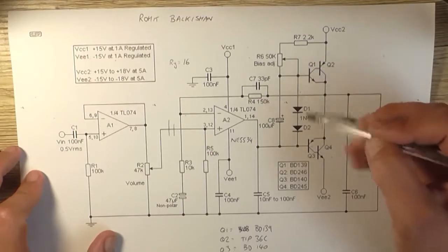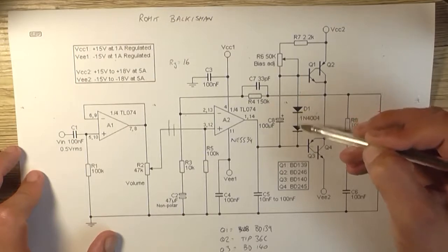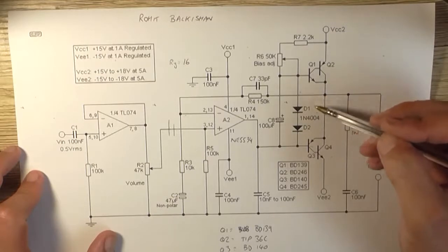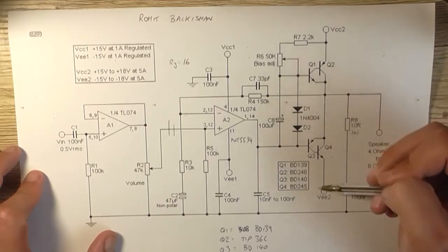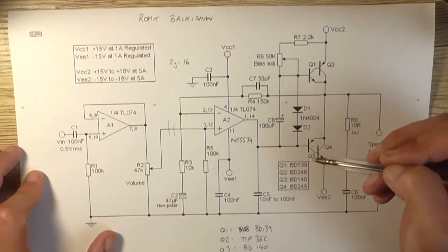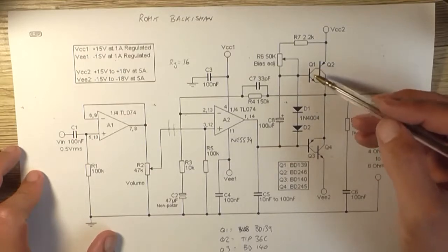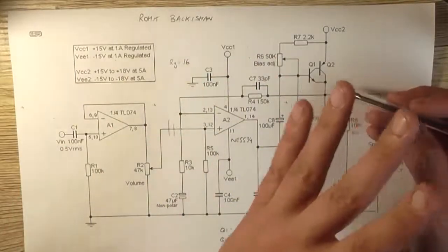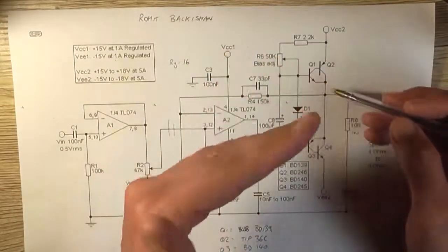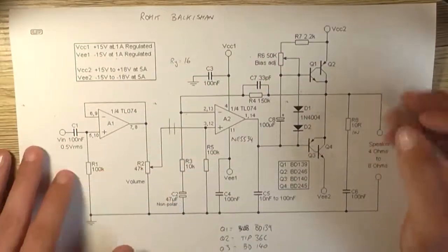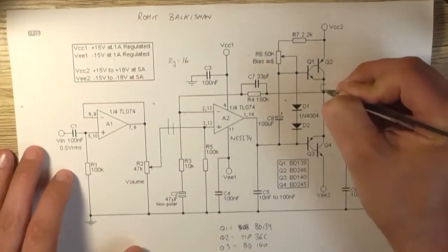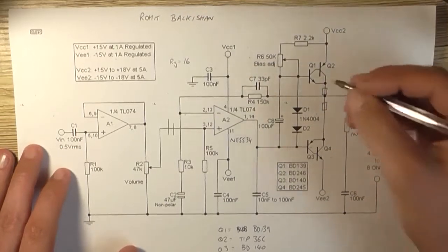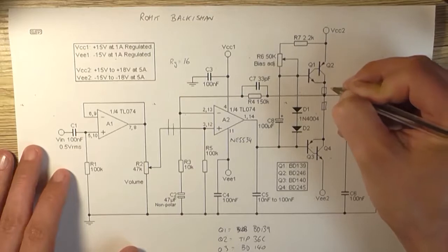Once the transistors heat up, the diodes conduct more, the bias goes down, and so therefore does the current flow through the circuit go down. What that means is it's to try and prevent thermal runaway. So once it starts heating up, it drops the current down to limit the amount of current flowing through the output. But really there should be two resistors here to help combat that thermal runaway